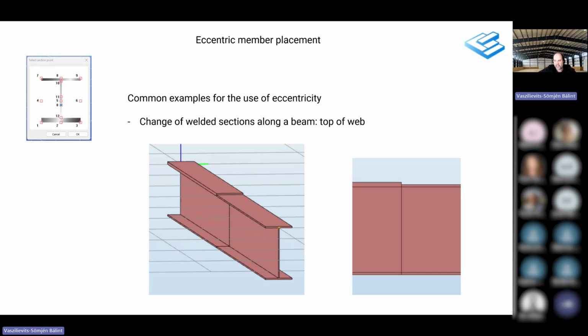The problem is not just that they are not well adjusted by the top of the web as I wanted, but they are also visibly very misplaced, because one element is at the location where I believe it makes sense, but the other is certainly shifted below due to the shift of the center of gravity relative to the mid-height of the profile. Now, I saw many projects where people didn't care too much and made the project like that and used it.